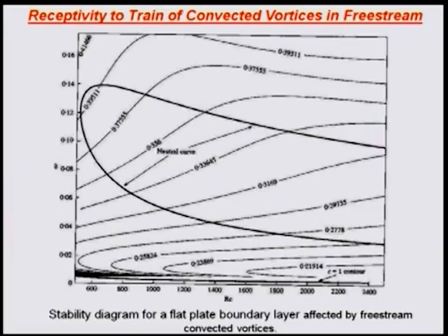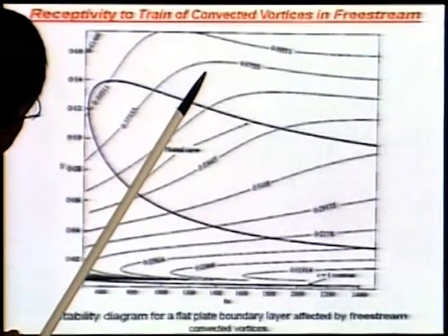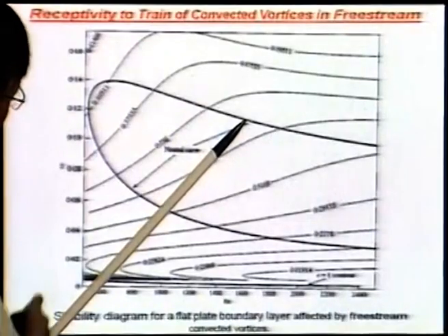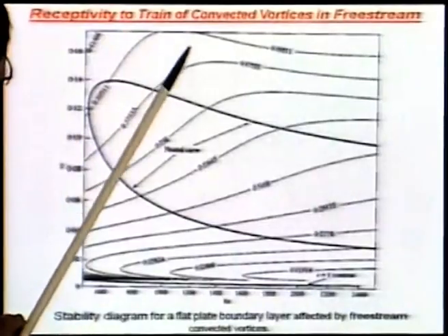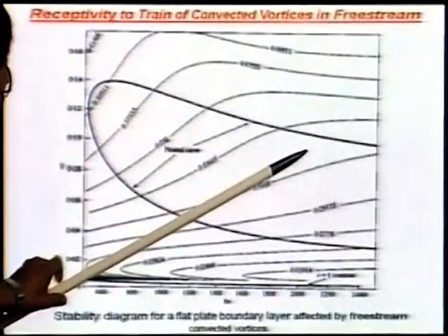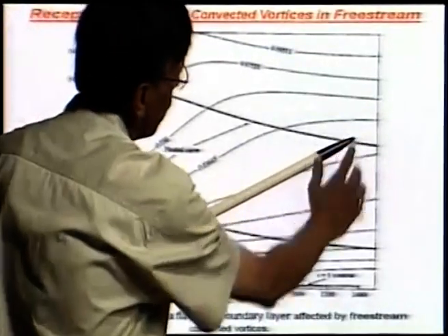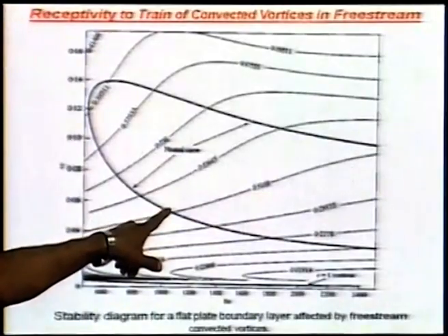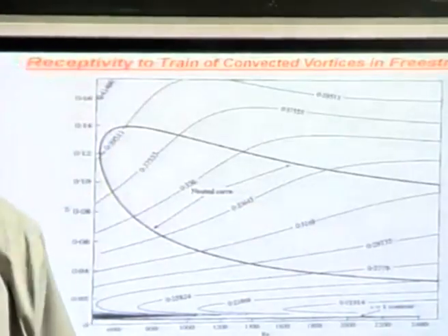And this very clearly shows that unlike your monochromatic wall excitation, where different frequency results correspond to different rays originating from 0, 0, and you can see even for low frequencies it does have a significant stretch, if you look at the corresponding c equal to constant line, it enters probably later, but it leaves the unstable region much later.